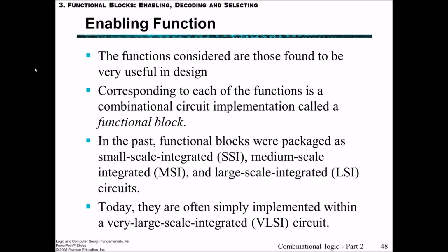In this part we're going to talk about the function blocks enabling, decoding and selecting, and that's going to provide the groundwork for talking about multiplexers in the next part. So enabling functions are really useful in design. Corresponding to each of the functions is a combinational circuit implementation called a function block. Historically, these function blocks have been packaged as small-scale integrated, medium-scale, and large-scale integrated circuits, but today they're often implemented simply as very large-scale integrated circuits, VLSI.